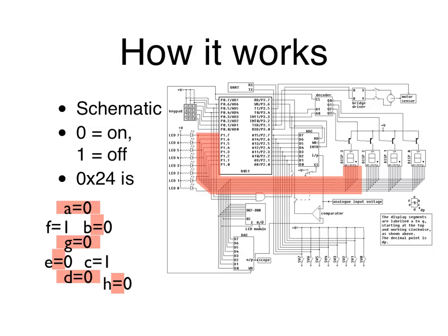But okay, anyway, just to give you a brief overview, we'll go over these much later, so you don't have to. But I'm just pointing out a few things you should pay attention to as software programmers. So oftentimes you'll see kind of strange things like this. Kind of zeros and ones are backwards from what you might expect. You might think 0 means turn off, 1 means turn on. But with embedded programming, a lot of times it's really the electrical consideration that forces you to have to do things backwards. Okay, and you have to know the reason why.